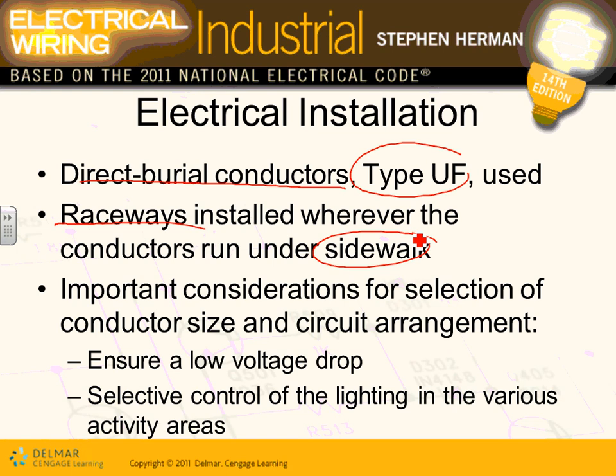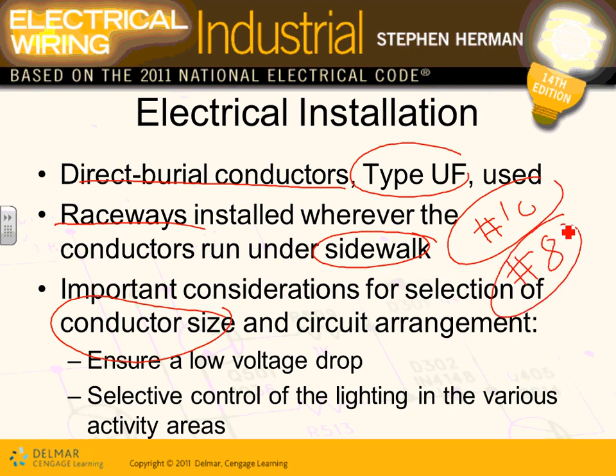When you select your conductors, guys, you don't want to use less than number 10 outdoor. I'm going to be looking at yours when you specify it. No smaller than number 10. Typically, number 8 is very common. And the reason, Adam, not because of the load, when we put a fixture outside, the reason we put a bigger conductor is because of voltage drop conservation. If you have a 20 amp circuit, typically I can use number 12 with it, right? Number 12 is fine. So we go to number 10 or number 8 because of voltage drop conservation.